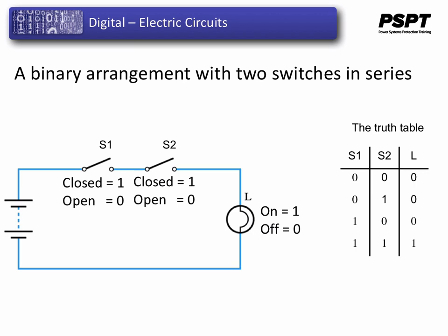The two switches form what is known in logic terms, or in gate terms, as an AND gate. We state that the light will be on, or L is equal to S1 and S2. In other words, the light is on when both switch 1 and switch 2 are on. And the truth table displays this, where you have zeros if either of the switches are off, but if both switches S1 and S2 are on, then you have a 1 for the light.